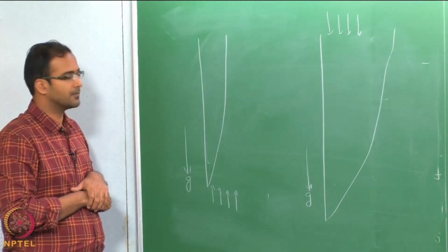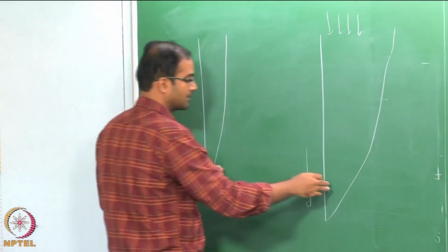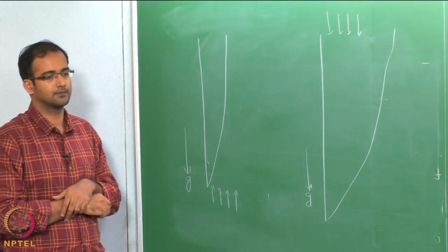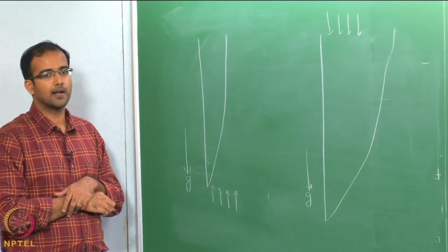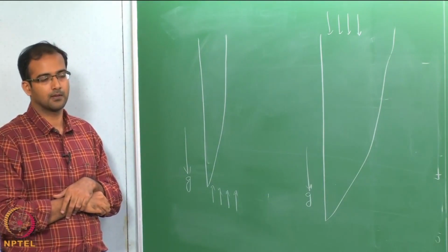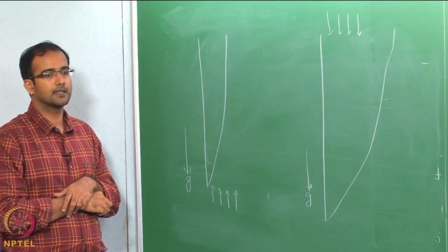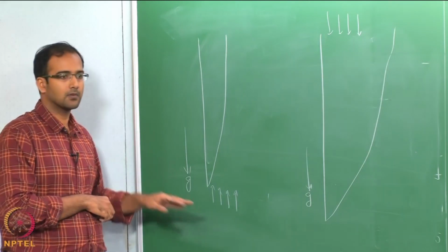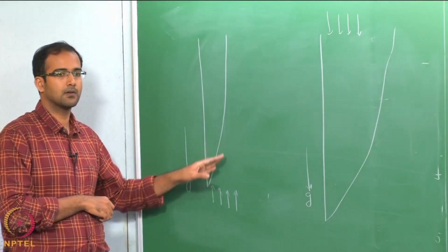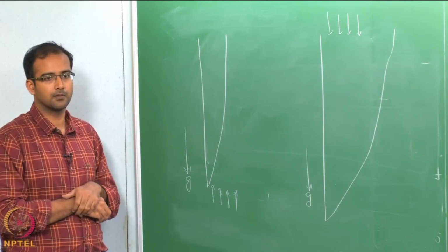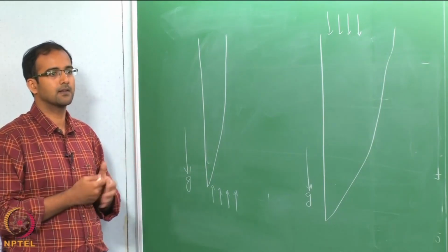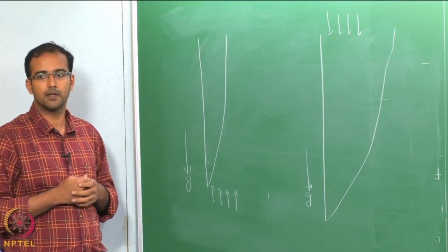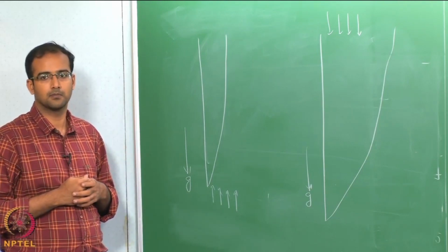Okay. So when we do these kinds of flows, what is the way to calculate the similarity solution? Is there a similarity solution for this problem? Well, the thing is, what is the correct similarity variable to use? Because when you talk about the forced convection boundary layer, we use the Blasius variable, but natural convection involves the Grashof number. So which similarity variable can we use to describe this problem?